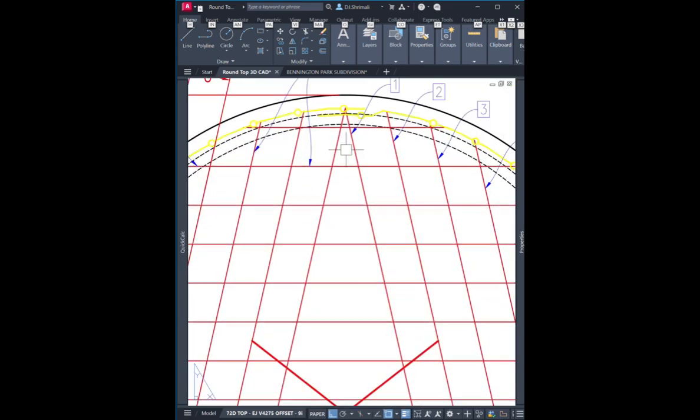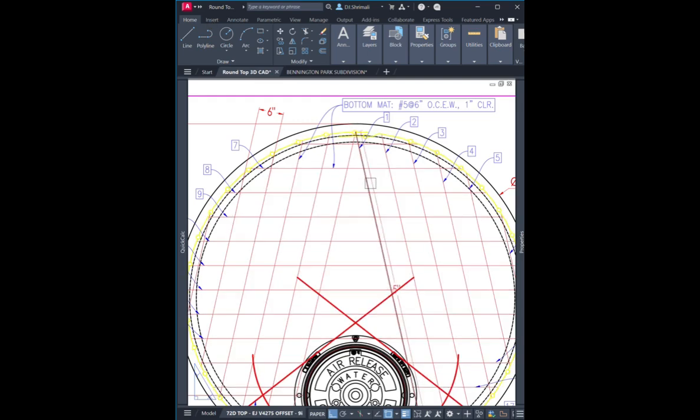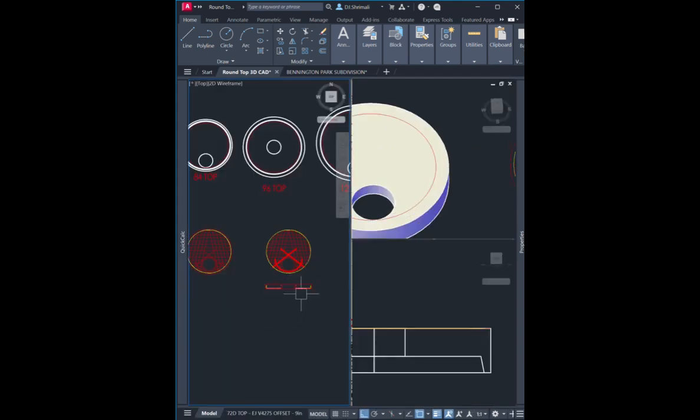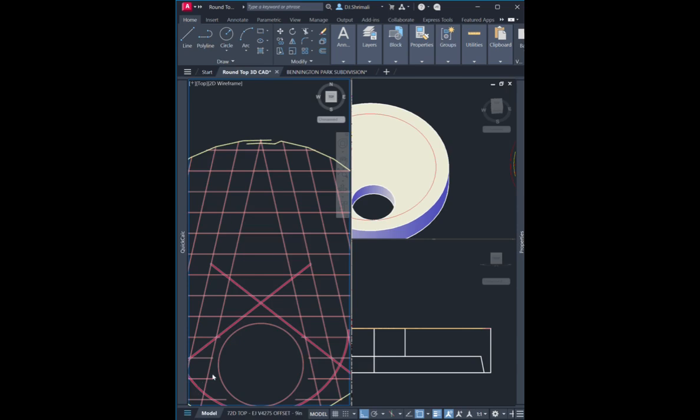If you measure it over here, it's not gonna give you the correct dimensions, since those are 2D lines. It's not part of a 3D object. If it was part of a 3D object and we had created all the rebars in 3D using cylinders, then when you measure it, it might give you the exact dimension, right? Or if you match that dimension with the actual scale dimension, then it might give you. But the easiest way that I think is to create another layout and then create a viewport in it, right?